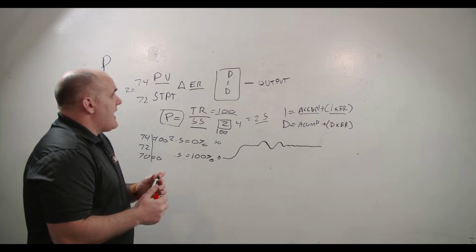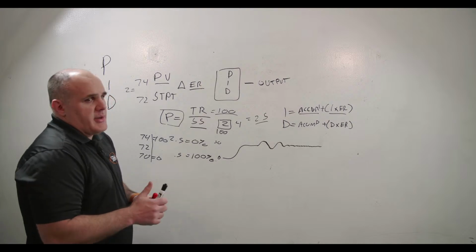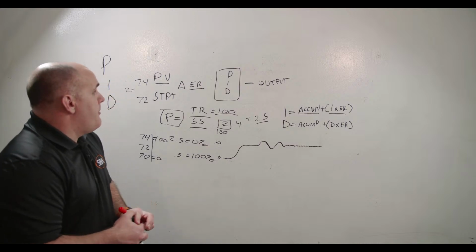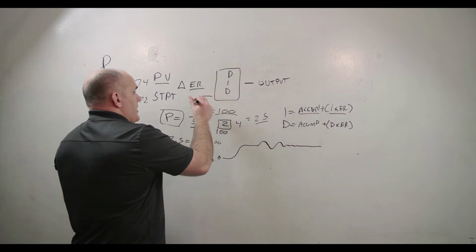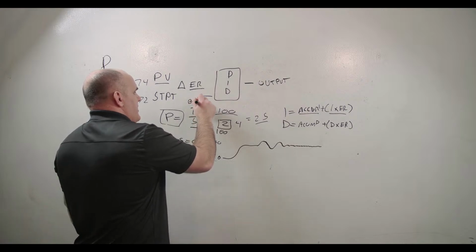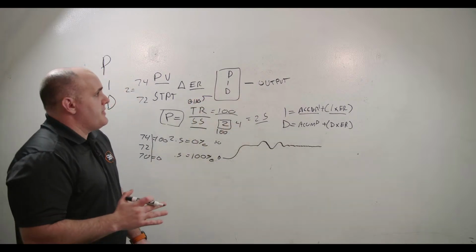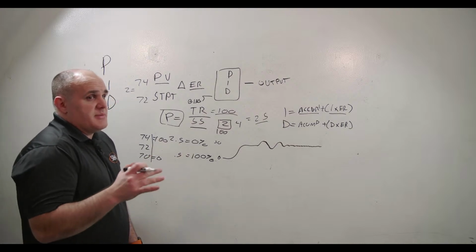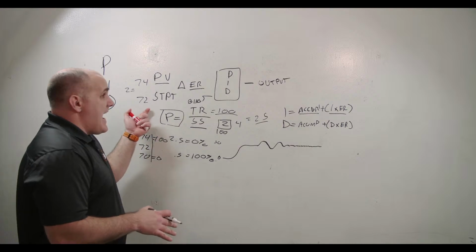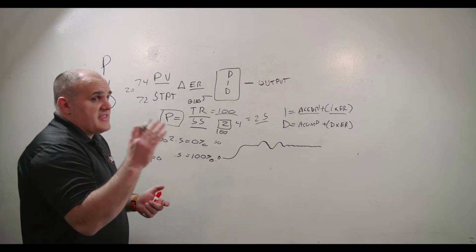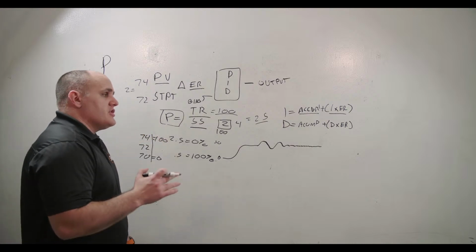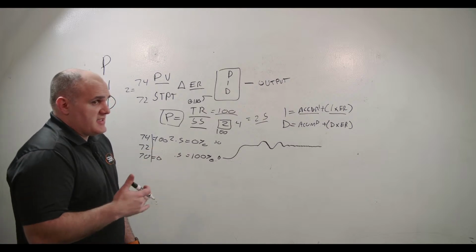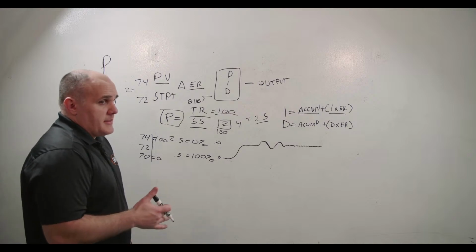Now, before I go through that, I do want to talk about bias, and I do want to talk about action. Okay, so bias, also known as startup value, I kind of hinted at it a little bit earlier. It's how you preload your PID loop controller. So for example, with a VAV box, we may want it to be preloaded to 50% at satisfied set point because we want that damper open in order to get that ventilation to satisfy ASHRAE 62.1 minimum ventilation requirements for spaces.